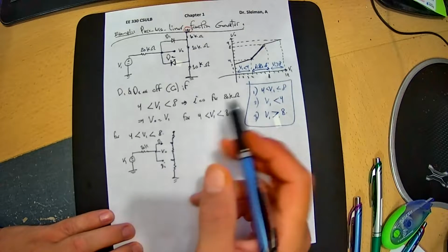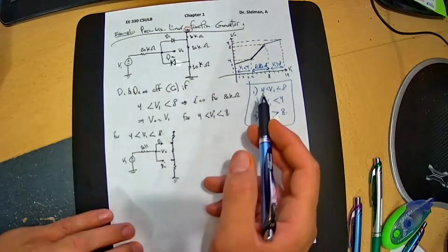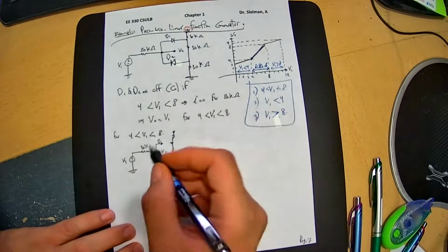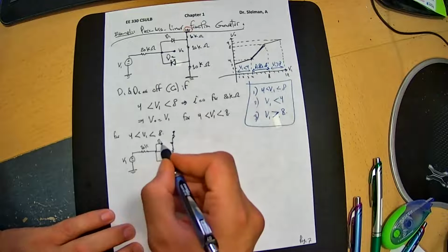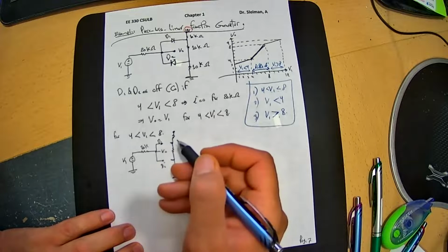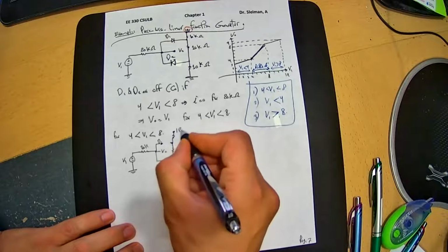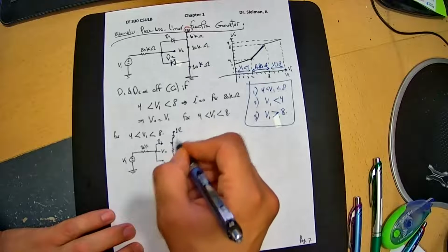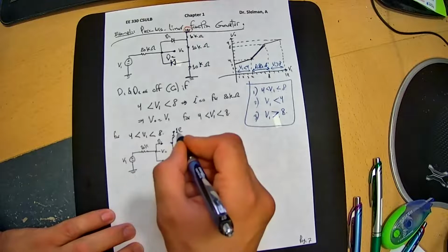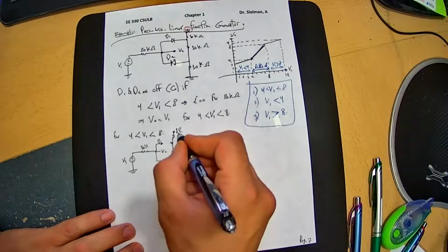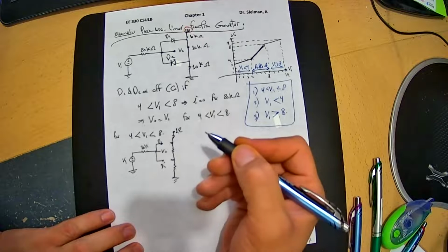it could be 10, 12, anything. So most likely forward bias on D2, there is no forward bias here because we have 12 here. In order to forward bias on 12, V1 has to be greater than 12. So this is going to be off.